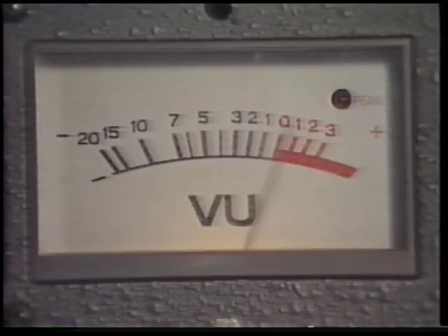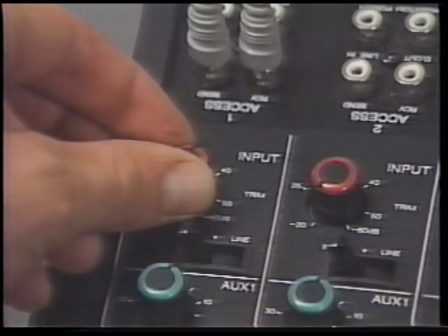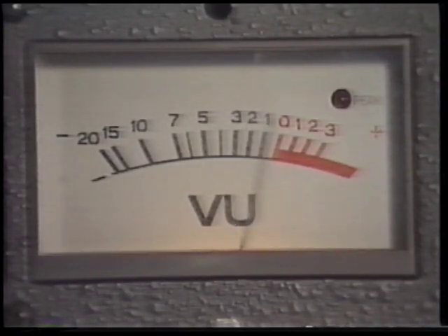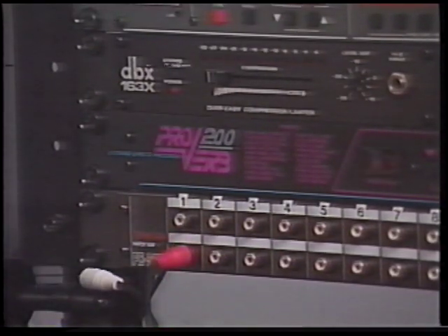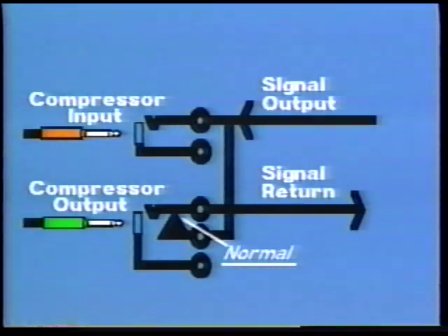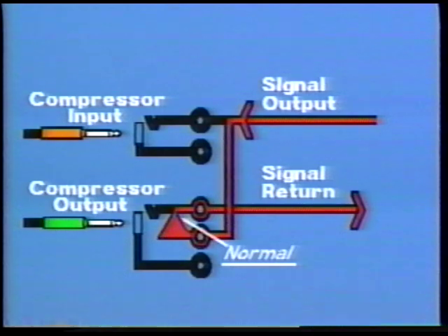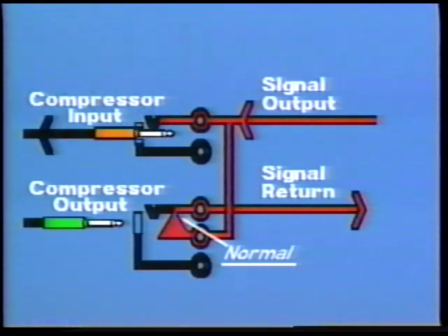The mic preamp should be set for a conservative peak level between -1 and +1 dB on the record meters. Once this normal signal level has been adjusted, you can then insert the compressor limiter. Connect the preamp out or access out to the compressor limiter input. If you have a normal patch bay, the compressor input can be connected without interrupting the normal signal path.